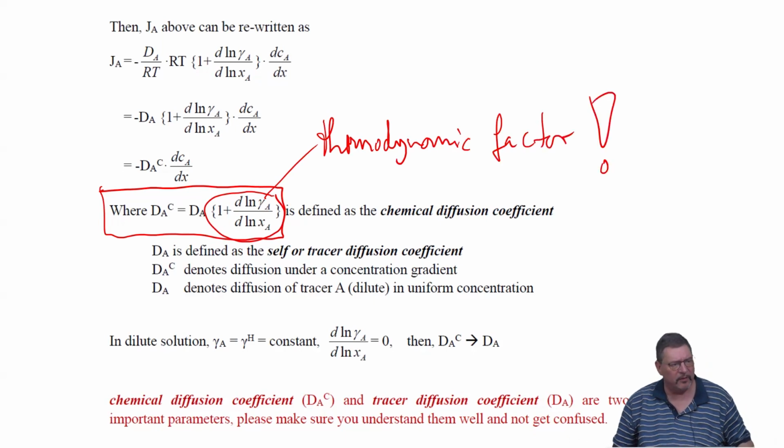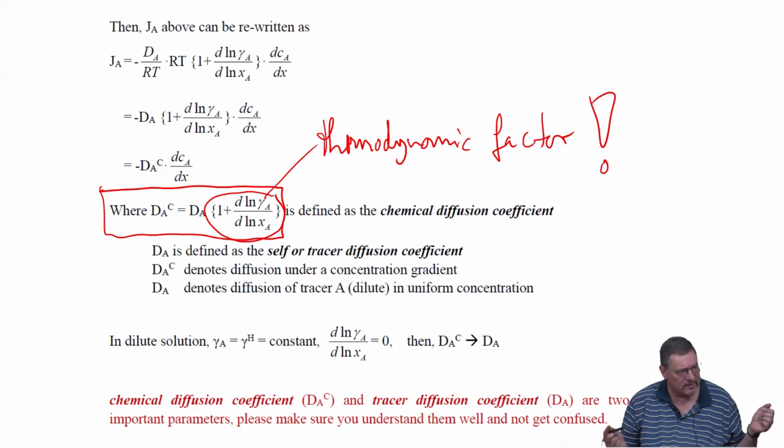And this thermodynamic factor basically takes into account that when you have interacting atomic species of different kinds, here only two, but in a high entropy system more than that, that the diffusional transport of constituent A depends also on how constituent B is transported. Right? So it's kind of correlating the diffusivities of the constituents. And you can see that when you now do an interdiffusion, well, maybe I write this one first.